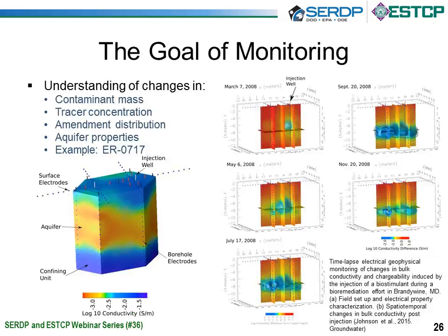So in terms of monitoring, Judy's going to talk a little bit about some monitoring examples, but monitoring is a potentially very powerful geophysical methodology, and it's increasingly being used. So instead of just going to a site with a bunch of geophysical equipment, laying out a survey, collecting the data and walking away, we can actually install geophysical sensors permanently or for the long term and acquire data over time. In the same way that you might put a probe in the ground and leave it there to collect data over time at a point in the subsurface, and I think we all know the benefits of doing that. We get temporal information, and our understanding of systems becomes a lot greater. We can do the same thing with geophysics today.